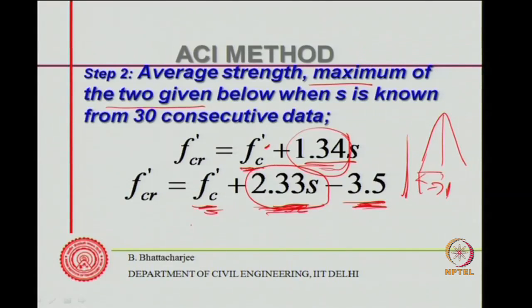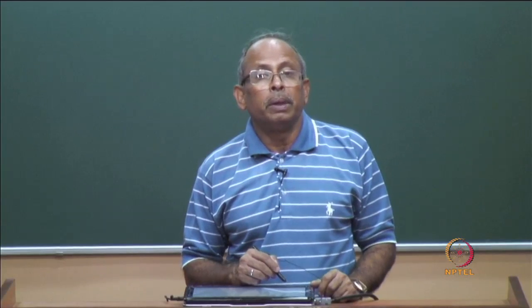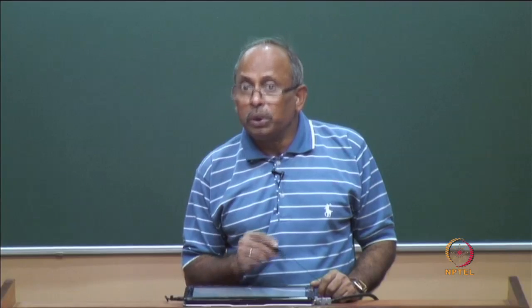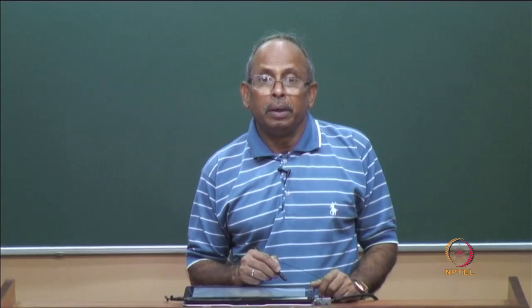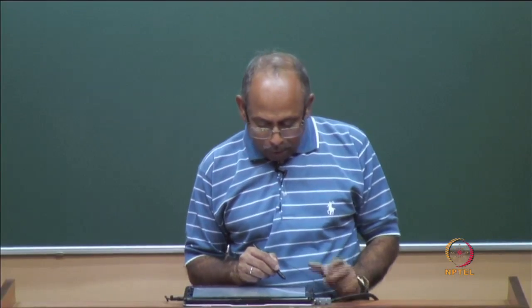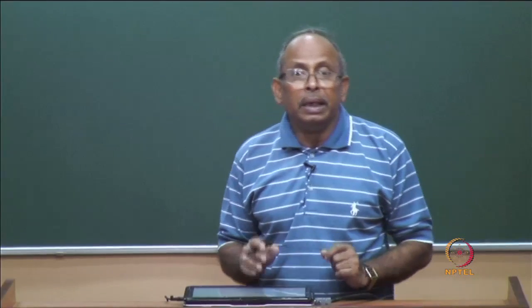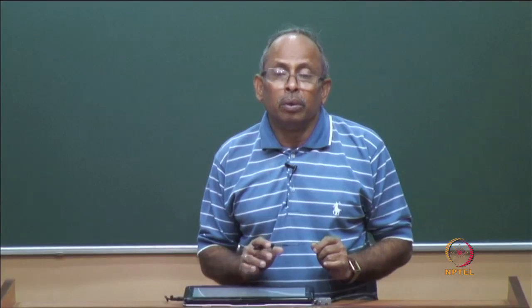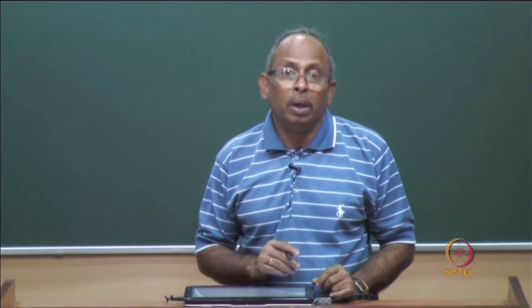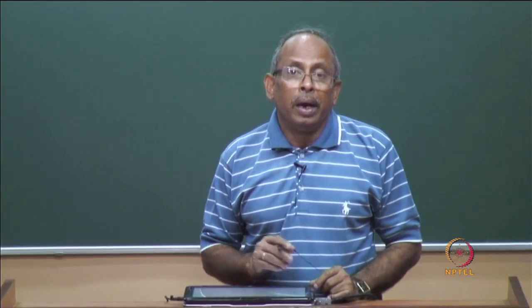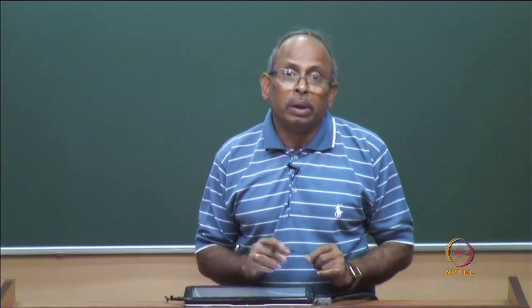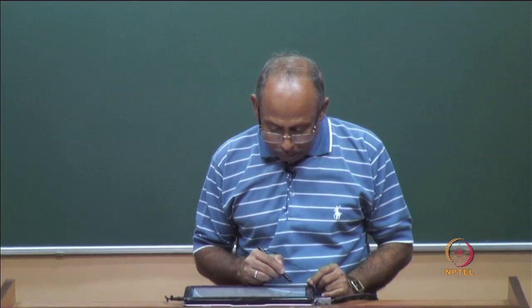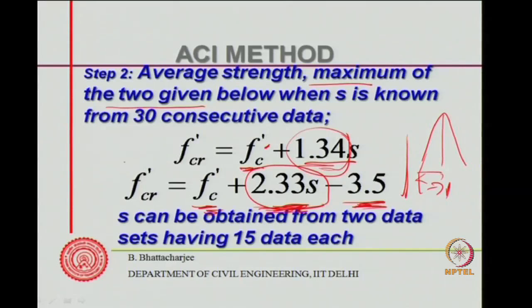So, you have found out the water cement ratio, and we have also found out the water content. Again I repeat, this is all for the cylinder strength. So, average cylinder strength is known, and therefore, correspondingly I found out the water cement ratio. And when I found out the water cement ratio, also the water content, I should be able to find out the cement content.